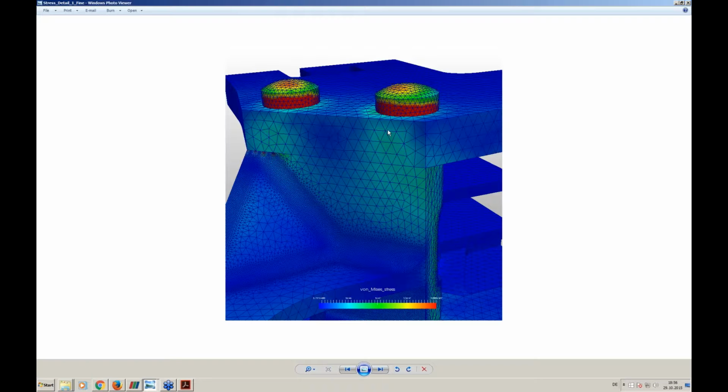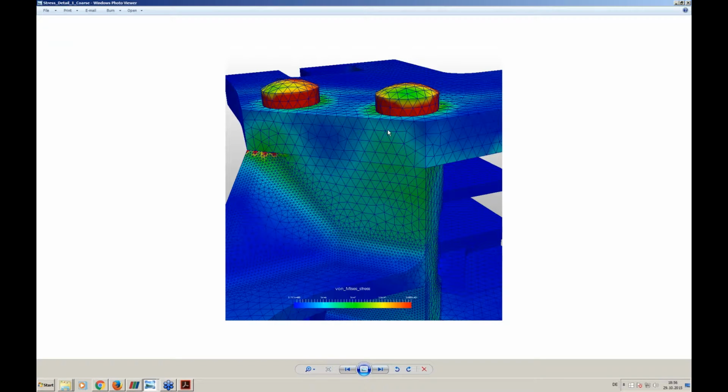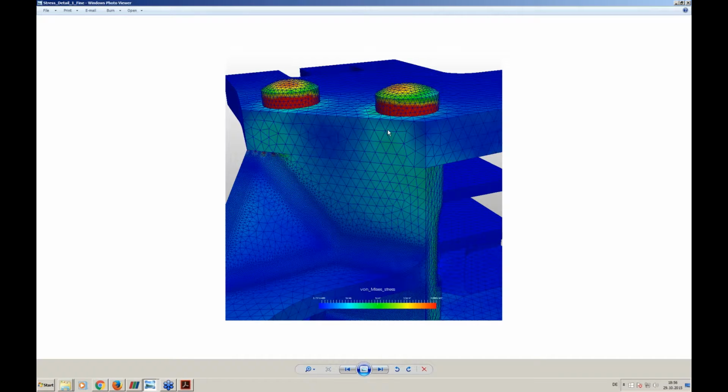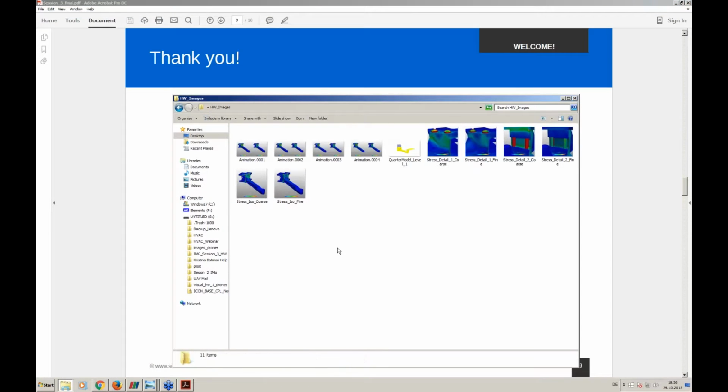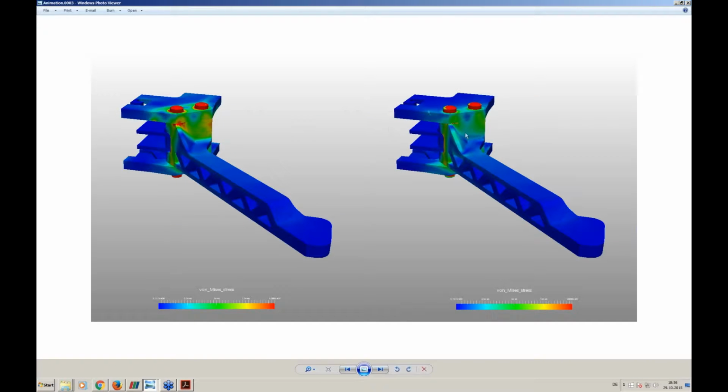The standard process there is really to start with, let's say, a coarser mesh, and then to refine it everywhere where we see, for example, high stresses. And you can really see that where there is a high stress, there is also a change when the mesh gets refined. So this so-called mesh independent solution is in the end what we are looking for. In this case, the difference will not be so big, so I think you can still use the coarser mesh for a first design decision.